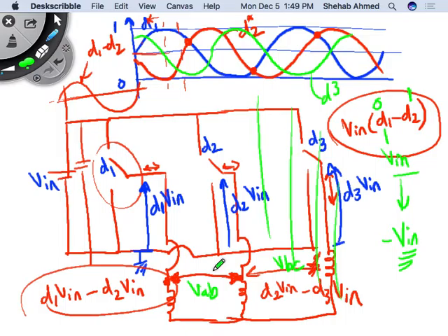And then calculation of losses, everything is very, very similar. Here the duty ratio is very different than in a DC converter. In DC converters, you typically have a fixed duty ratio. Here, if you want to be very precise in calculation of losses, you have to account for each pulse and each pulse width because the duty cycle keeps changing. Or you can just assume a certain average value for the pulse width and calculate losses with a back of the envelope type calculation. You don't have to be very precise because it's already approximate.